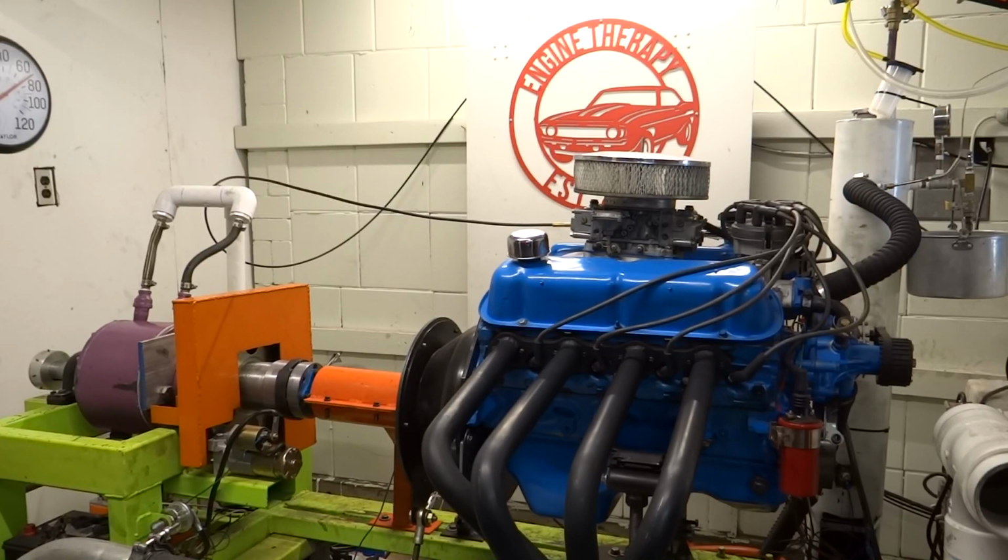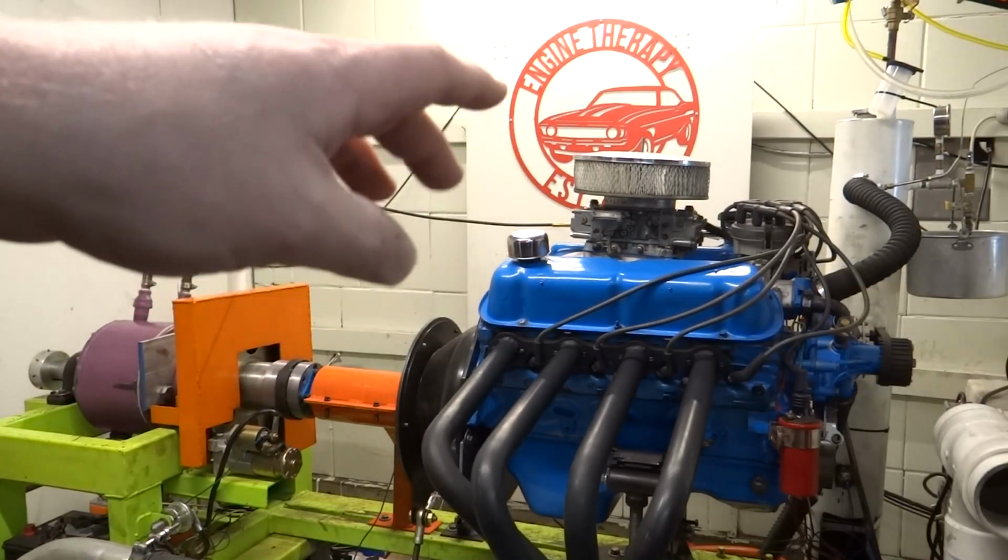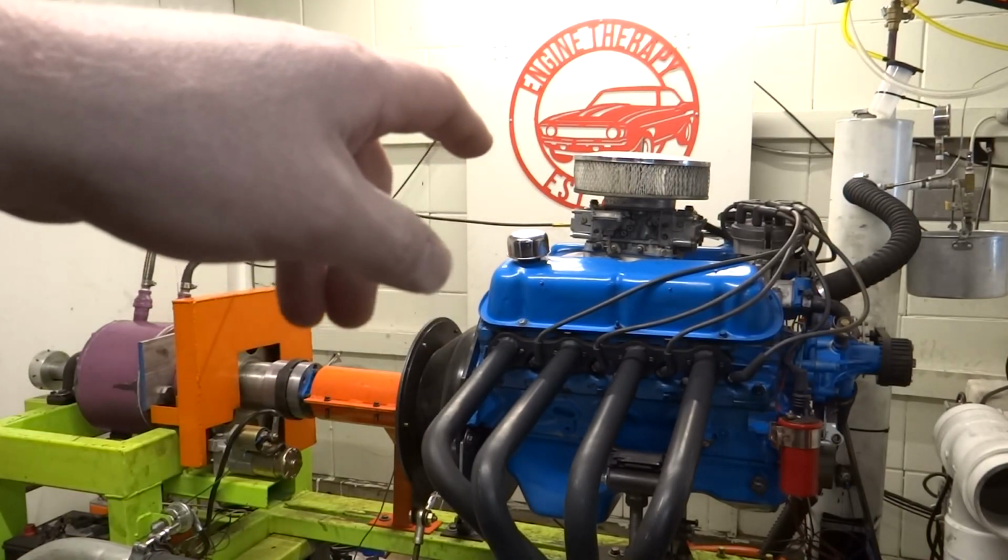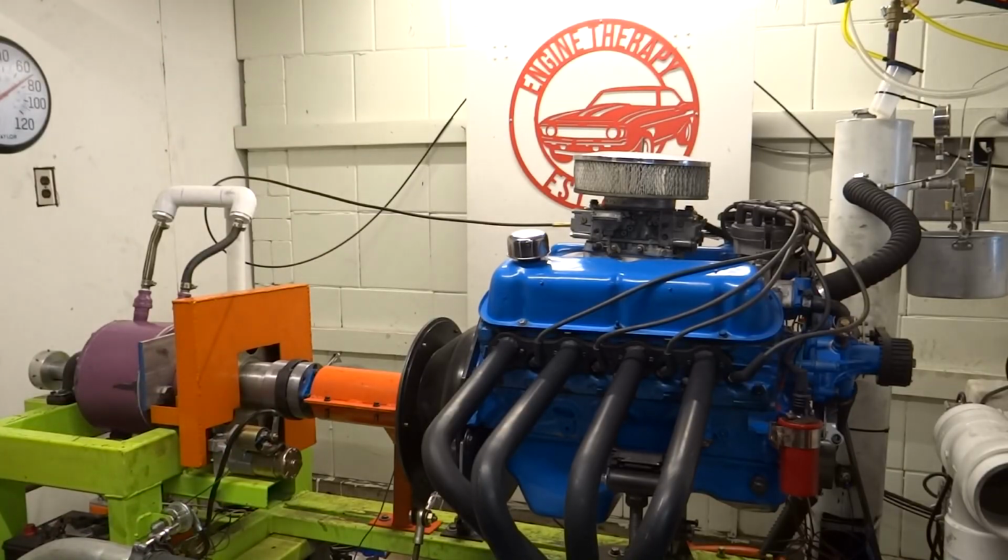But there are correction equations to correct the engine's power output based on, like I said, the atmospheric conditions. The way I got started with this is that I did some research and ended up buying an SAE paper, and of course it's copyrighted, so I can't really show you it. It's the SAE J1349. To my knowledge, it's meant for engine manufacturers who want to get an SAE horsepower certification. They need to follow a set of standards when they're doing their test, so that the test is being done fairly and in a repeatable way.